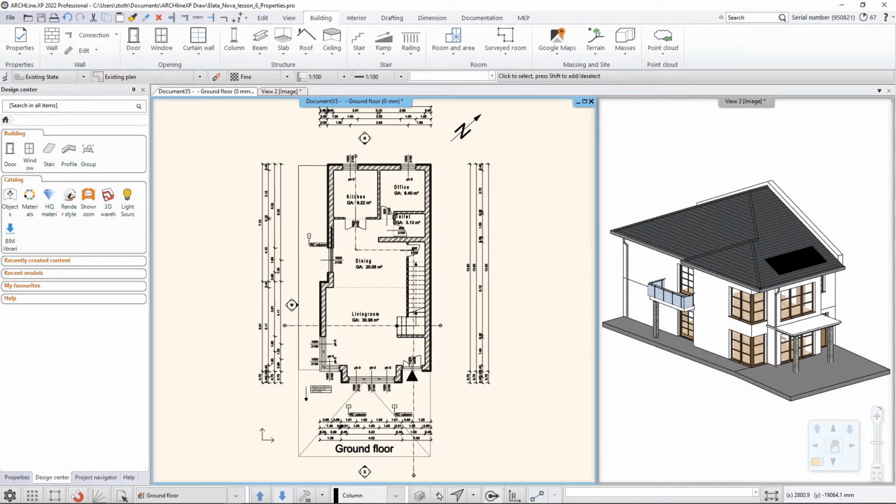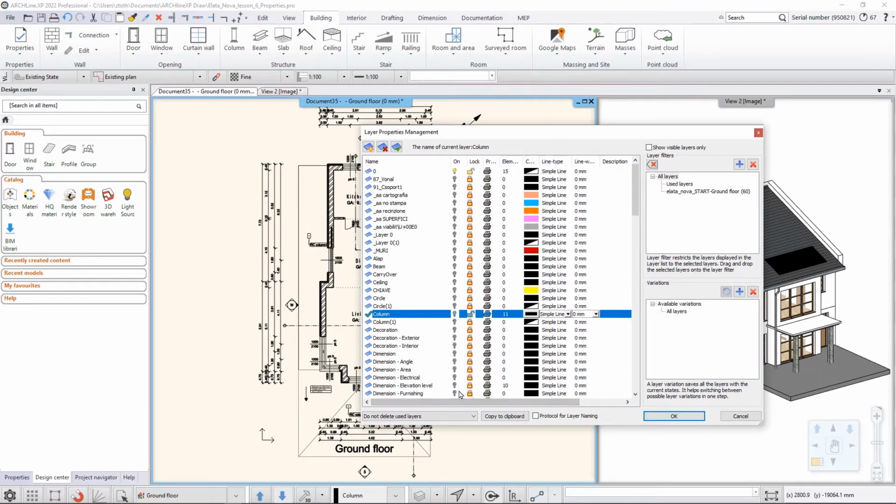This is what you can find in this little menu here. If you click on that, you will find the layer manager. This is the first item. If you click on that, the layer properties manager will automatically appear, and here you have a list of layers that you can not only list, you can also rename them by simply clicking on their names. You can change their visibility, whether they are editable, and you can also control whether they are to be printed. I will talk about this a little bit later.